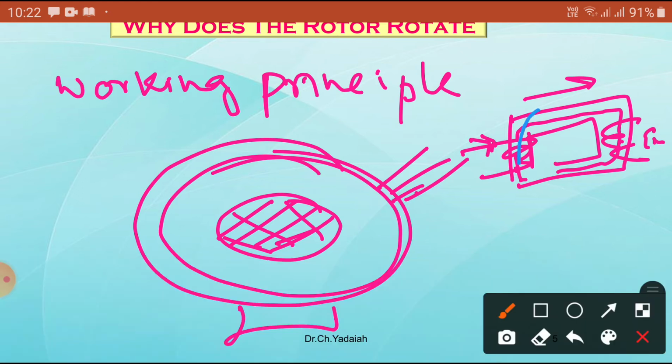So this magnetic field that is flowing through the core material links with the stationary secondary coil. Because of the AC supply, d phi by dt, that is equal EMF, is induced in the secondary coil as per Faraday's laws of electromagnetic induction.